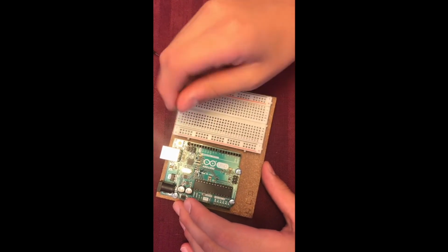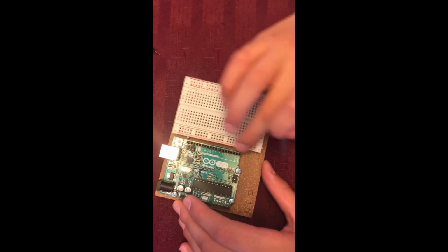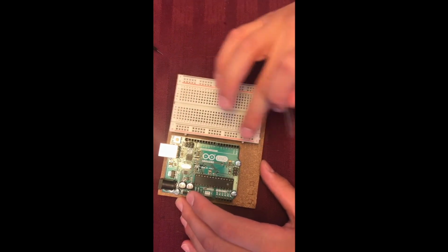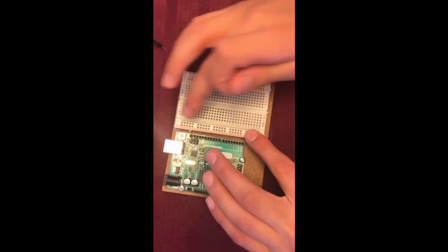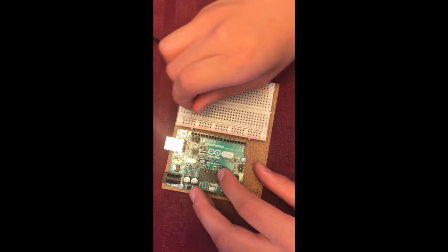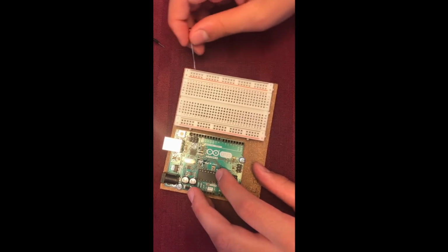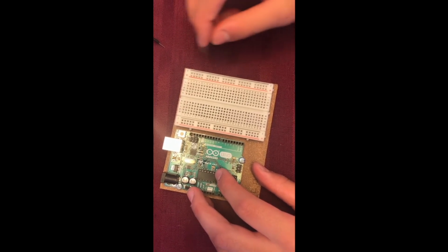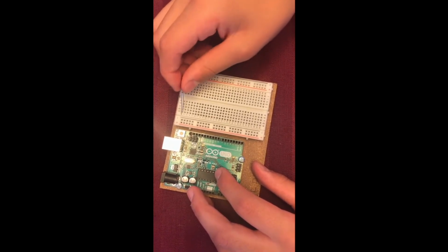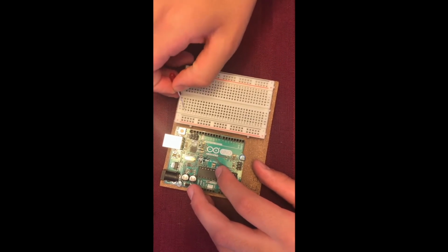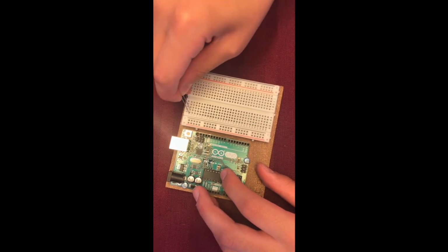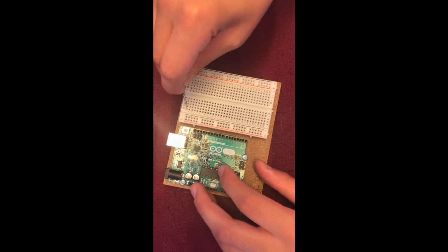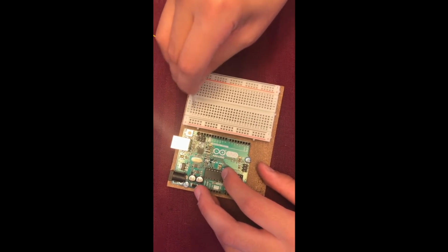these strips, the plus is actually connected vertically, and the minus is also connected vertically. So these two are not connected together, but they're connected vertically. So the whole plus connected vertically, the minus connected vertically. And same thing for here. And then these things, the rows here, they're all connected horizontally. So horizontally connected, horizontally connected, horizontally connected.